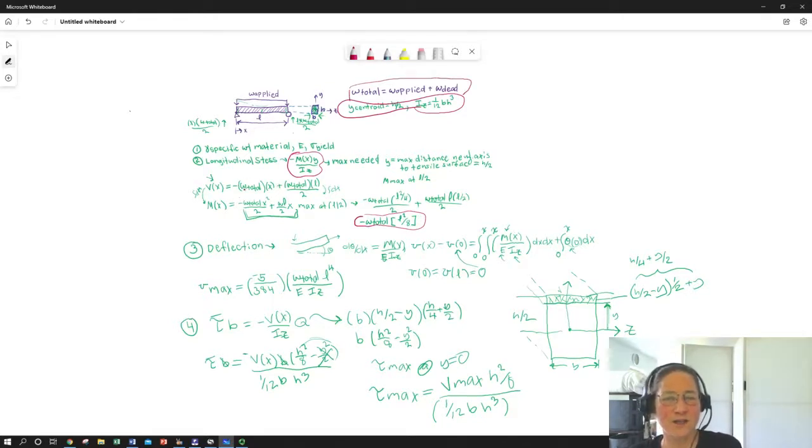I've got max shear. I could write an equation for max shear. It will be at the ends: total distributed load times L over 2, V max. These are all expressions that I'm going to need.